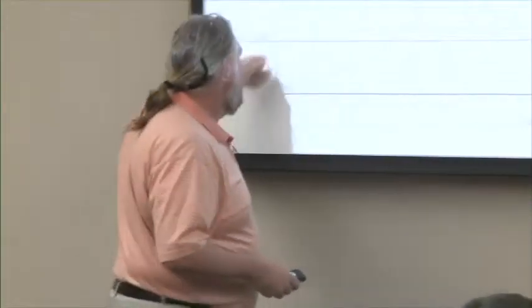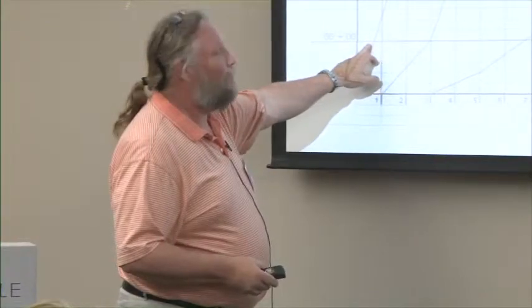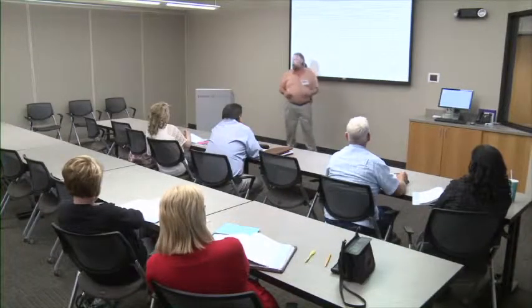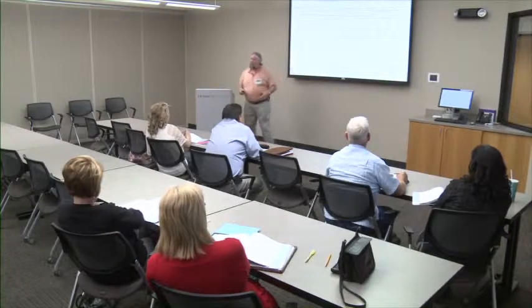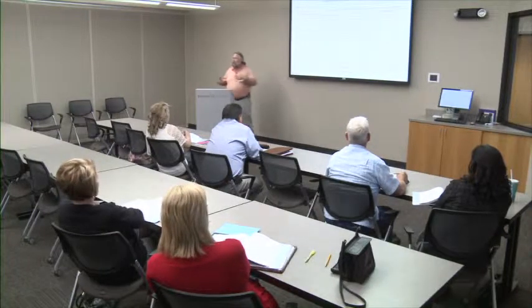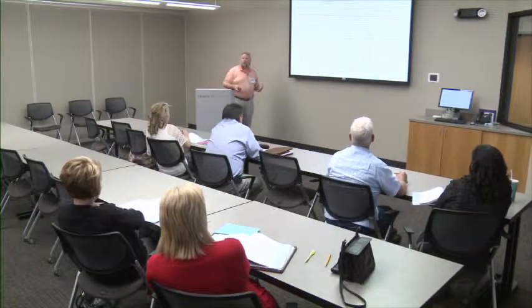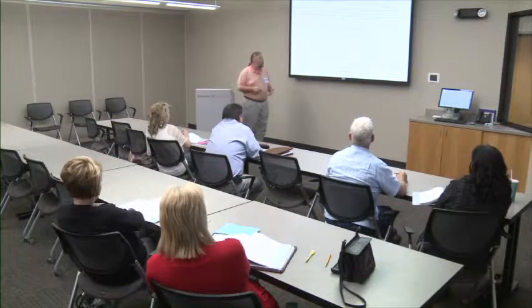So we can see at station 50, the following items are going to be going on at the same time on certain days. You know, here we do the stripping and the survey and layout, but on day 15, we're actually paving at that same station. So linear lets us look at it as we're going down the line. It works really good for highway projects, streets, things like that, but not very good for buildings.